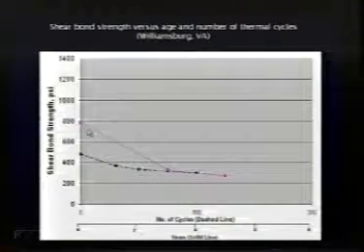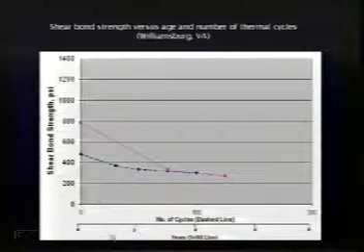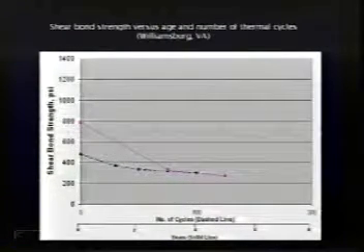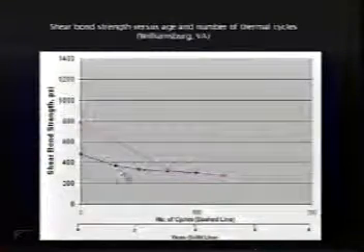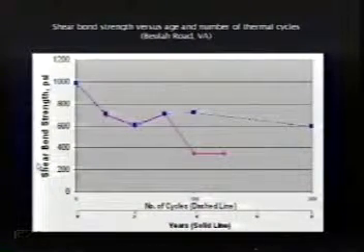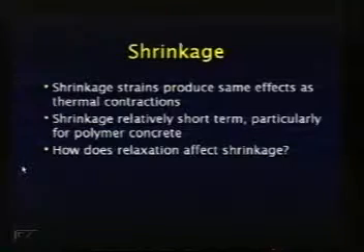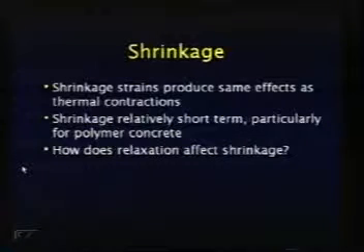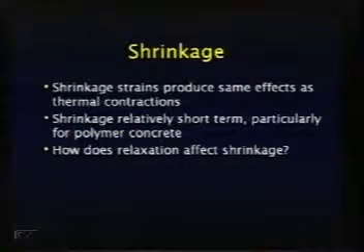This is one in which he measured shear bond strength, both as a function of number of cycles and years, and again, a pretty good drop-off in strength. Go and flip through this fairly quickly, but everyone who's measured bond strength with time has almost always found there is a reduction in bond strength between the overlay and the concrete.